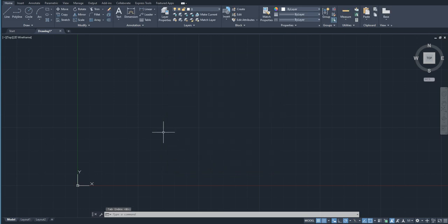If you can see that nothing has changed, don't worry, it doesn't mean that your AutoCAD has malfunctioned. The snap will not work unless and until you have any command active. So I'll just activate the line command now. And you see how the cursor moves only at the intersection of the grid lines. So this is what basically the snap settings, putting the snap on does.